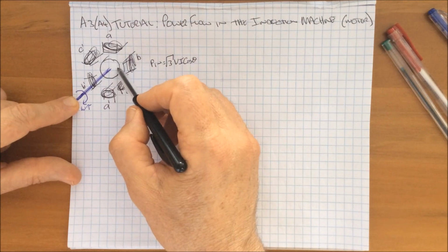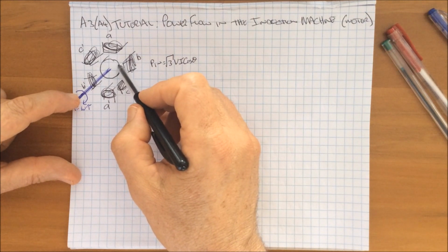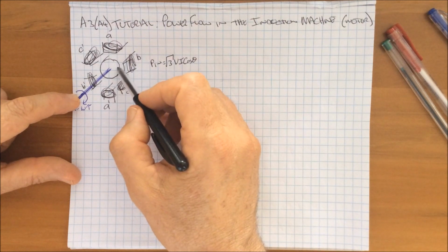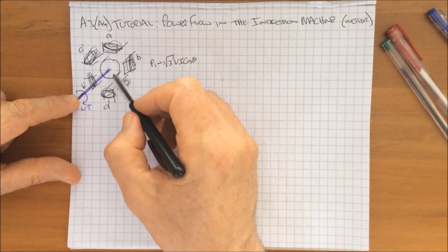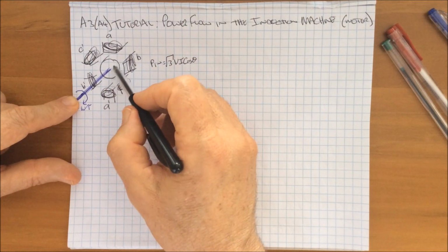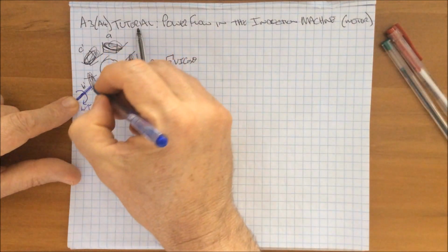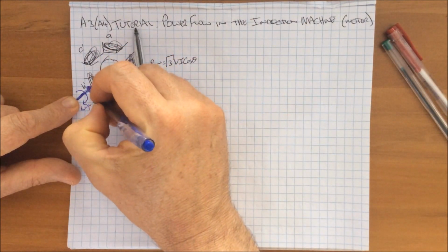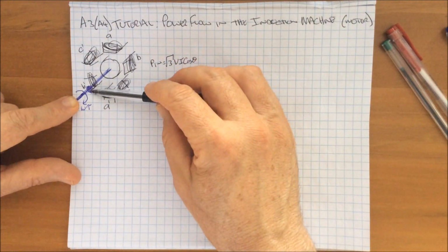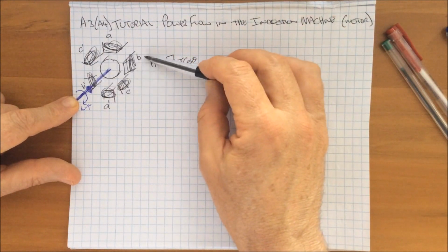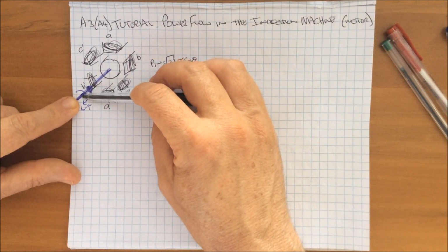The rotor is typically made of aluminium, with lamination, so again that will have a resistance in the rotor, and also the impedance associated with that. This whole rotor and shaft is sitting on a set of bearings. We can sort of pretend we can draw some bearings here like that. These bearings will have a resistance, so there's power loss there. So all through the process, as the power flows in, we're losing little bits of power all the way through.